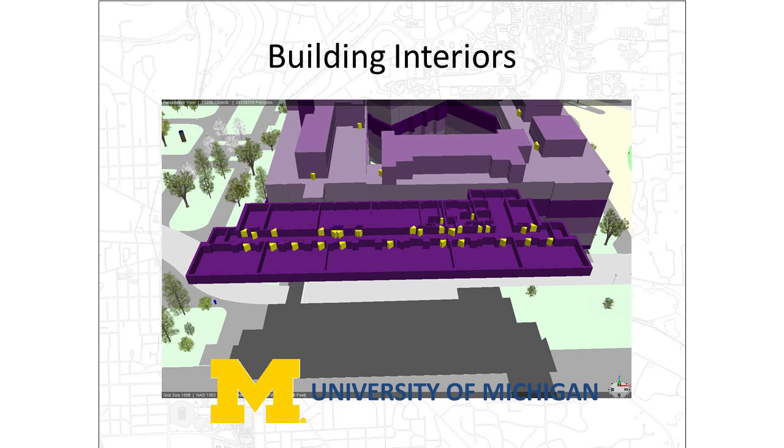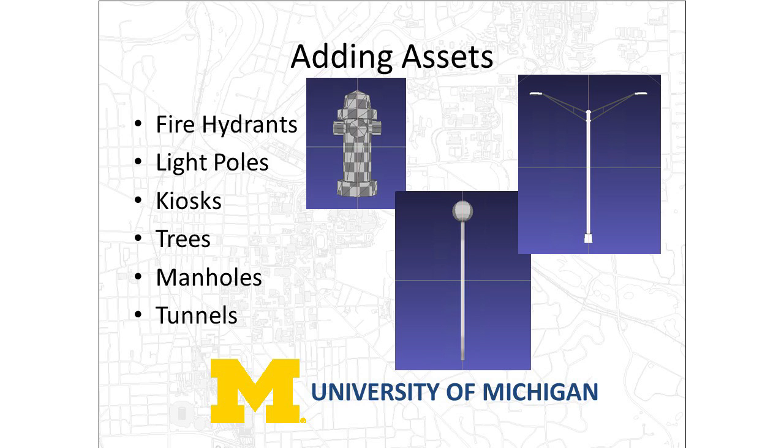You can do interiors through a CGA rule. I can turn off the rest of the floors. Here I've extruded the floor up just 5 feet, and the doors are in there. Then we can place assets in there if we want. I've only gone up 5 feet for a couple of reasons. One, it's easier to see over the room, but the other real reason is that we don't have good data on what our real door heights are. We've got excellent data on widths, but we don't have heights. And we don't have the difference between the drop ceiling and what the true floor ceiling is in our data. So it comes back to the question, is your 2D data really ready for 3D?